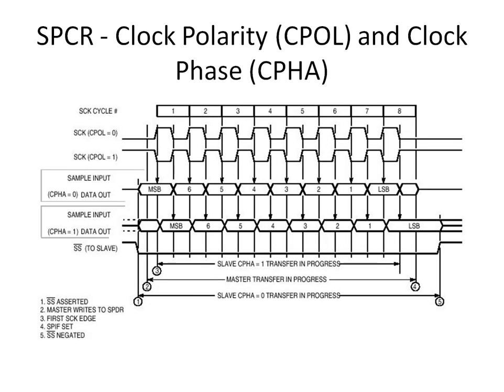So in using this diagram here, we're able to figure out which CPOL and CPHA value that we need, whether we need to set them to both high or to both low, or one is 0 and the other a 1, or vice versa. But what we're looking at here is the clock itself, the rising and the falling edges of the clock, and when the data is valid or when it's stable.